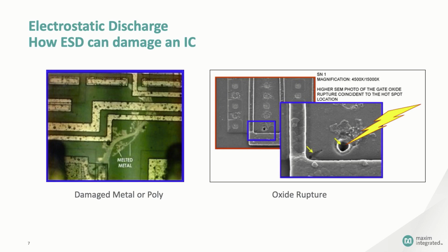Electrostatic discharge causes localized heating that exceeds the melting point of the dielectric material, in this case, glass. This damage can destroy the functionality of a semiconductor device in two ways. First, for just an instant during the discharge event, the conduction path is carrying a tremendous current. This current can vaporize the tiny conductors etched into the active layers of the chip. Suddenly, where you had a conduction path before, you have none, and the device stops working.